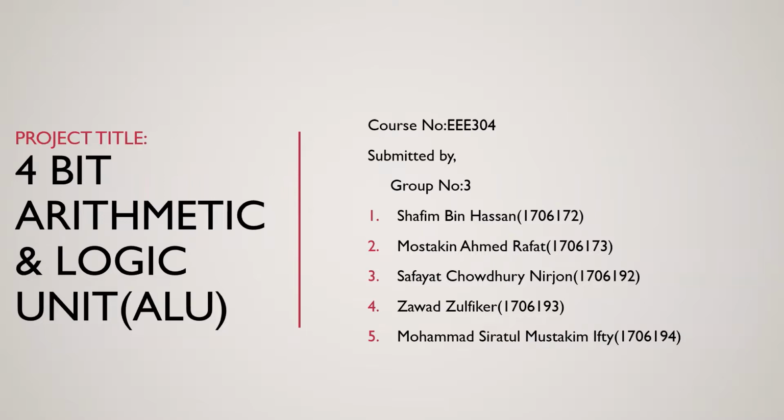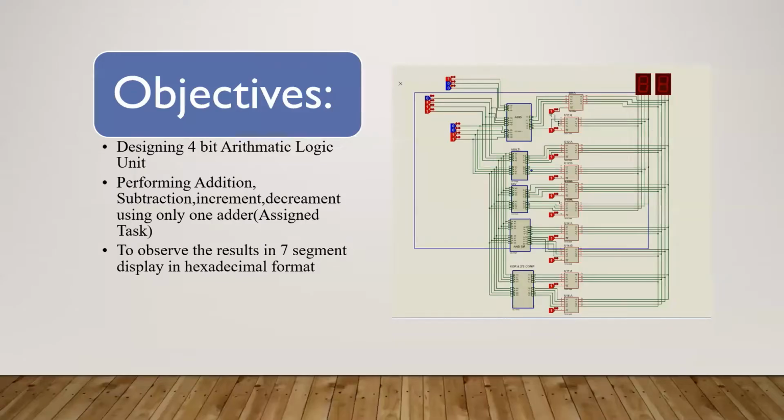Here we are presenting the project of Digital Electronic Laboratory, and the project title is 4-bit Arithmetic Logic Unit. Our main goal of the project is to implement logical and arithmetic operational circuits which perform addition, subtraction, increment, decrement using only an adder. And finally, to observe the output results in a 7-segment display in hexadecimal format.